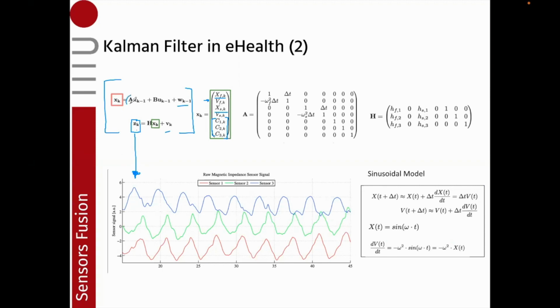Let's now define the transition elements, so the 2 matrices, A and H. To do this, we need to have a model. The model here is the sinusoidal model that, as we will see in a moment, tries to represent the state signal X as a sinusoid locally. And we use a process that is called, in some reference books, the extended Kalman filter.